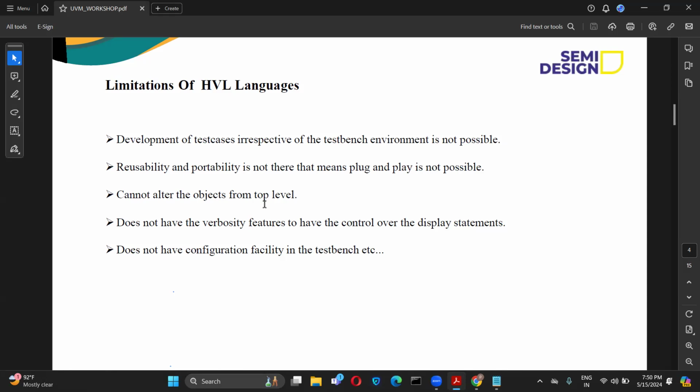For example, when we have started the coding of the driver, you can write in the UVM info "driver coding started". We do that to debug, to find out whether the processes are reaching the driver or things are stuck before that. To find all those things, we have the different verbosity levels.